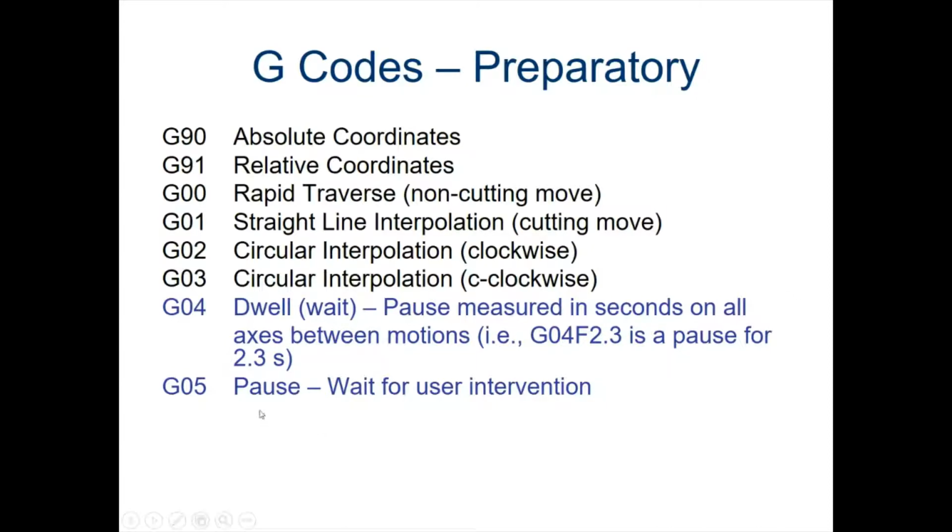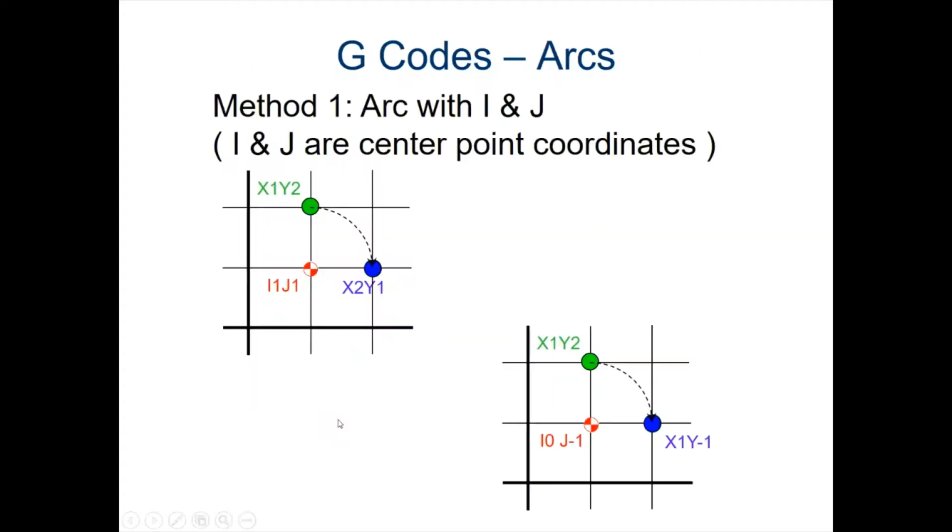Same thing for pause. You might put a pause in there because you're going to need to go in and do something. We don't ever really do that because we're going to do a tool change or something like that. We will use a tool change command and that will take care of that. But if you have some individual step where, between this step and that step, you needed to wait for something to happen, you can put a pause in there.